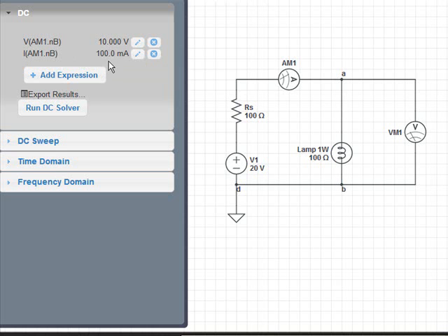Calculate the power. The power is equal to voltage times the current. This can be found in my other lab file and you can fill that in. Then you're going to calculate the resistance. For here, you're going to use the formula power is equal to V squared over R, solved for R. And those two measurements should match.